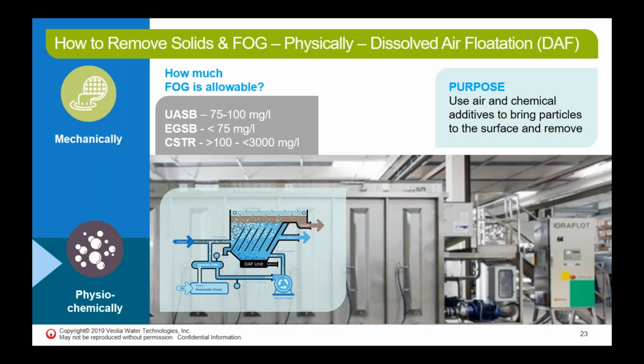And even in the gravity separators, we would always see what we call a skim layer on the top of the particles that just naturally tend to accumulate on the top. In a lot of cases in the lighter industries, we see a lot of fats, oils, and grease tending to float to the top. So with the addition of chemistry, we sometimes apply the technology that is called dissolved air flotation, where we introduce effervescence bubbles.